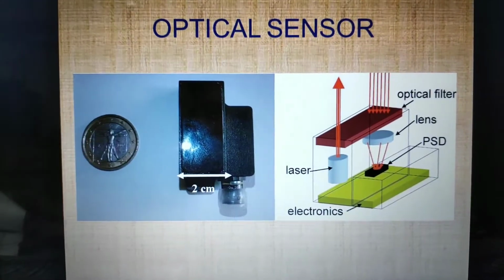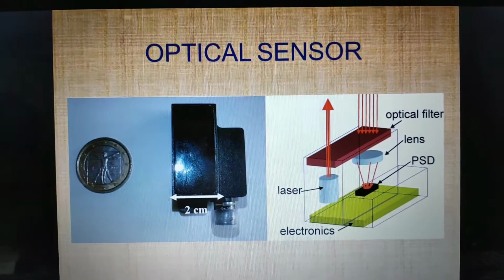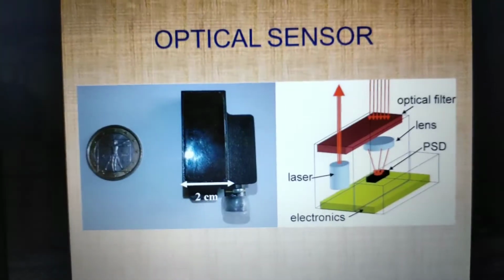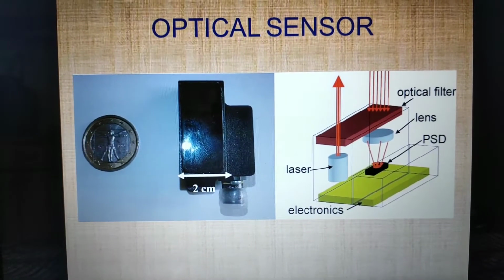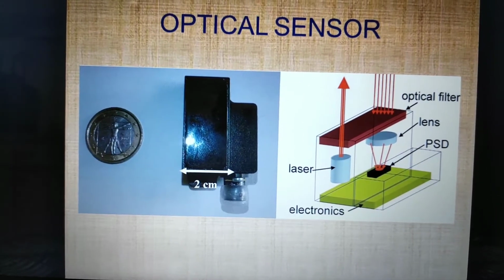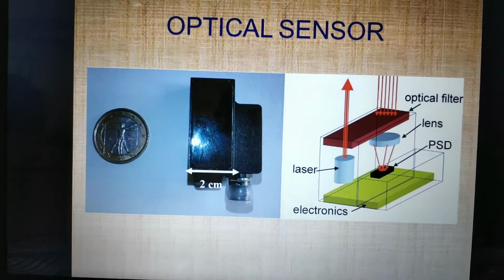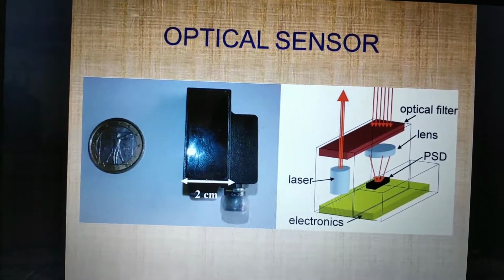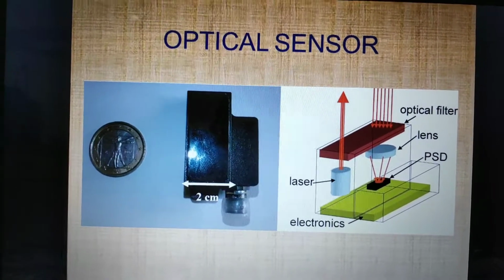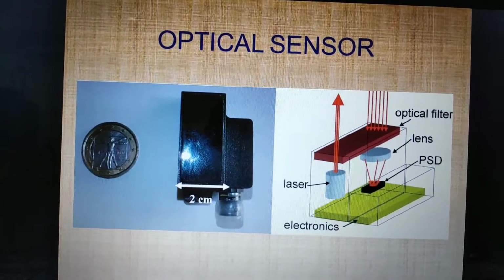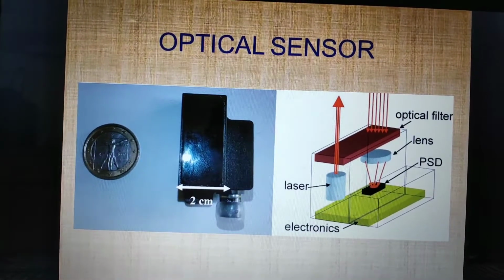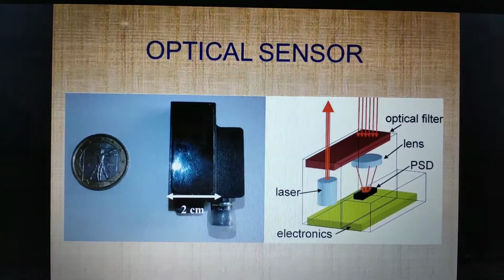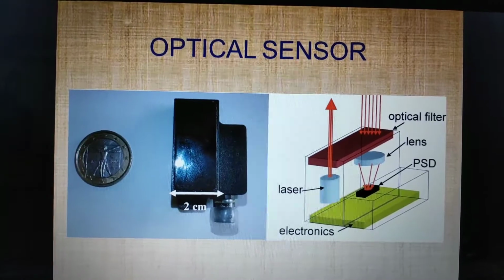In this photodiode, we can use a laser. The full form of laser is light amplification by stimulated emission of radiation. In the figure we can see the motor and the vehicle speed sensor, and the photocoupler consists of an infrared beam directed onto the photodiode. The infrared beam is interrupted by the light-shielding motor rotor that is driven by the speedometer drive. In this way, the light sensing element is switched on or off at a frequency that is related to the speed, and this optical sensor may be used in many applications where electromagnetic sensors are used.